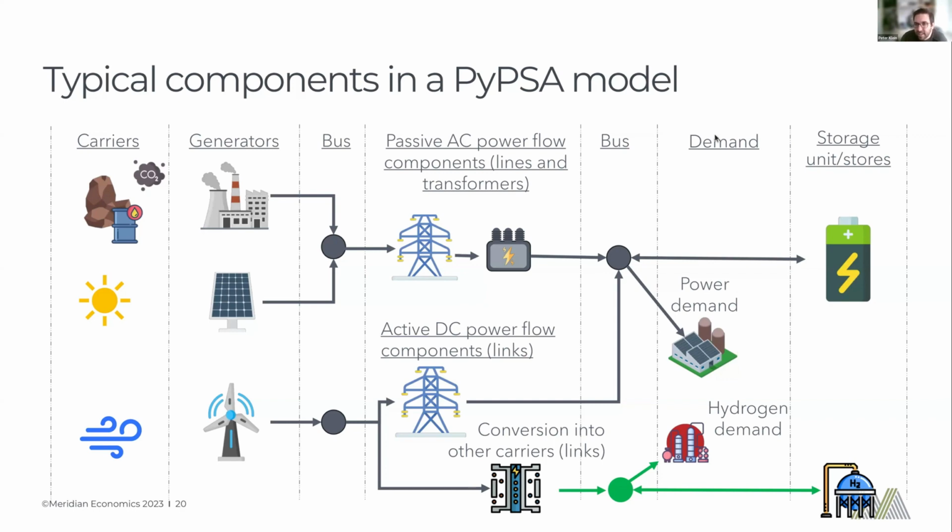The next category is loads. A load can sit at a bus, and it withdraws power from the network. It's also possible to model negative generators. A negative generator can represent a load, but it gives you a bit more flexibility. For example, you can have price sensitive loads by modeling them through a negative generator.